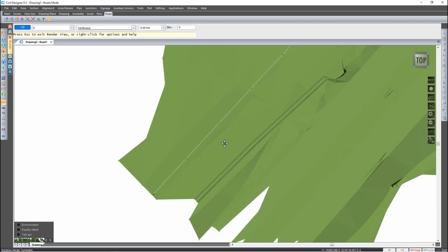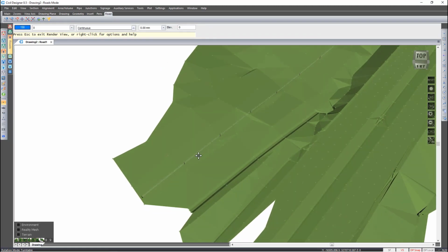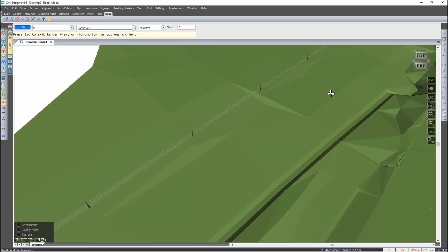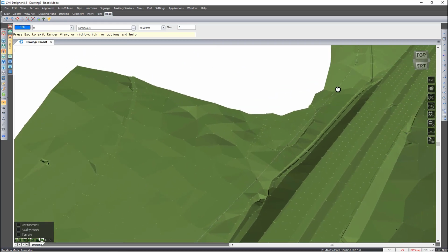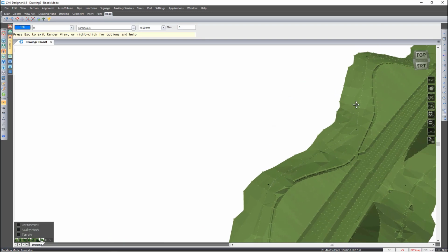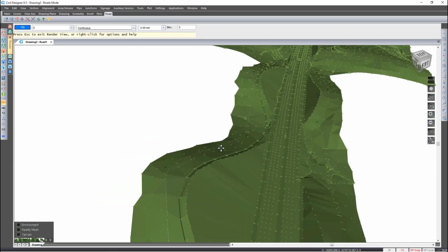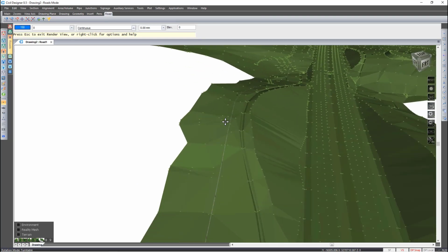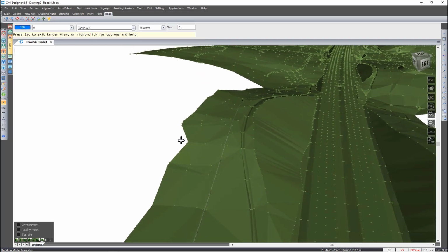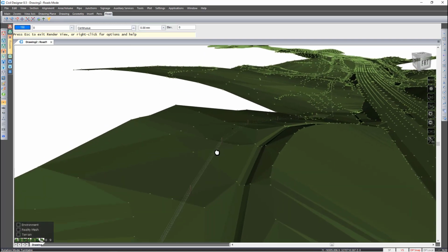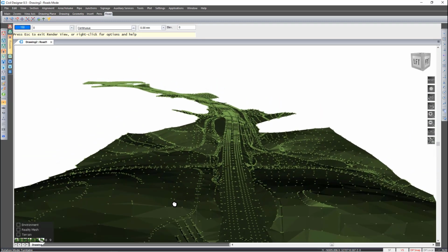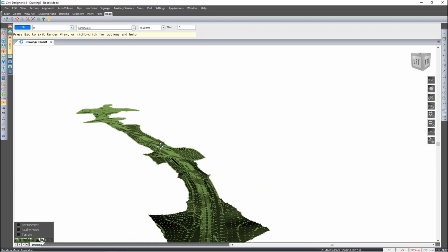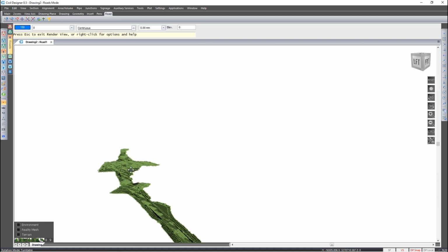If we were to zoom in now, you can see that the fence has been applied along the length of our original polyline, and it's using the ground level for elevations. Now you can see the actual length of this fence, and that is why I feel that you could really benefit from using this Draft Expert to save you a huge amount of time. You can imagine how long it would take to manually draw that fence along the entire length of your road reserve.